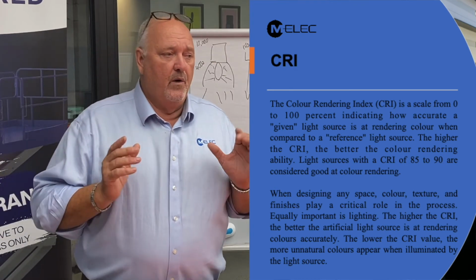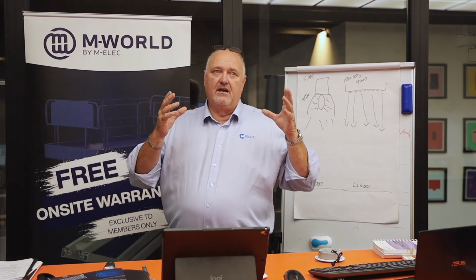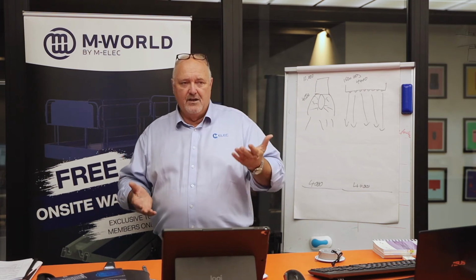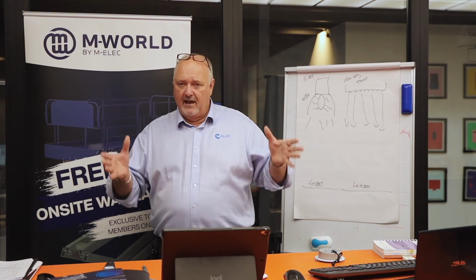When you're doing a dress shop, for example, you want a high CRI because you want to show the true colours of all the apparel in and around the shelving. If you're in a dealership, you want a high CRI. If you're in a nursing home and you're trying to create a relaxed atmosphere, you might go for a lower CRI, a warmer colour, to keep everybody relaxed.